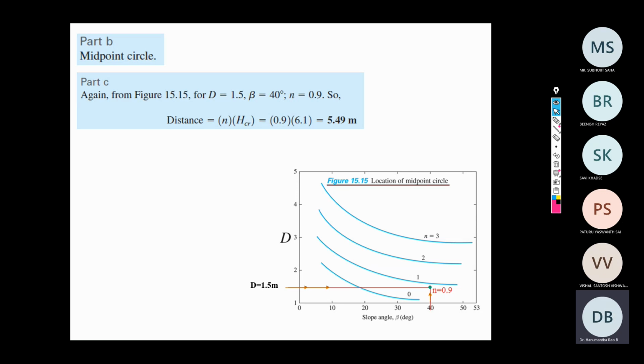Now the third part is. Then it should be, sir, base failure, not slope failure, no, sir? No, it is a base failure, because the hard layer exists just below the toe, sir. Correct. And in slope failure, the failure plane is passing through the slope, sir. Correct.